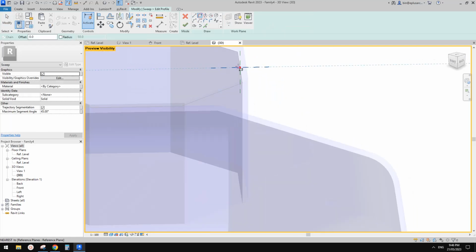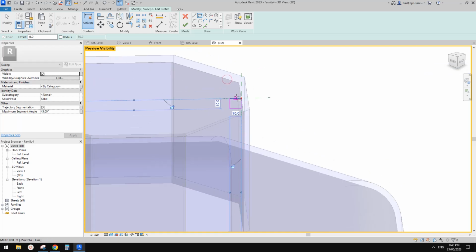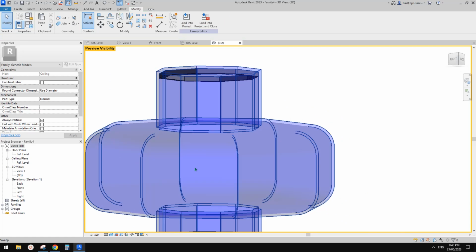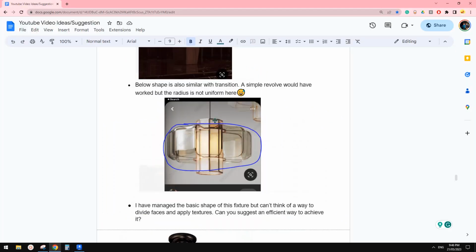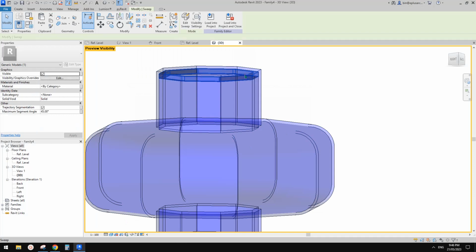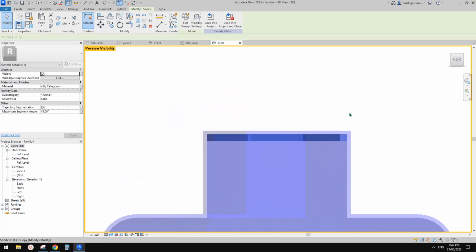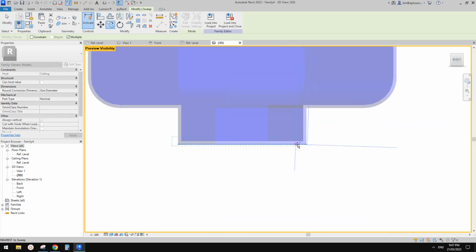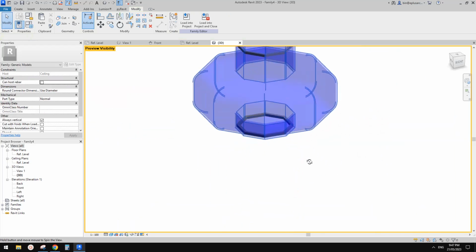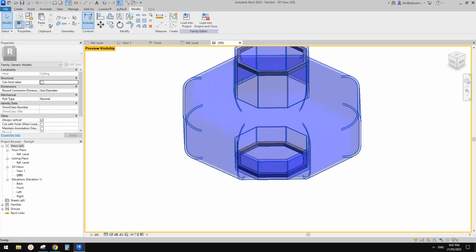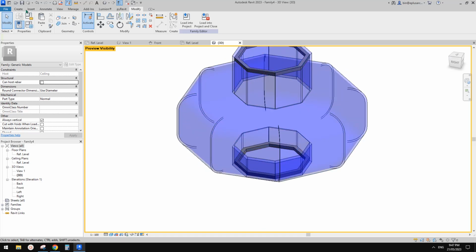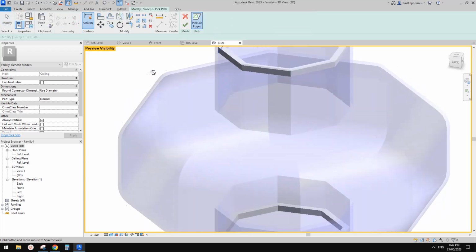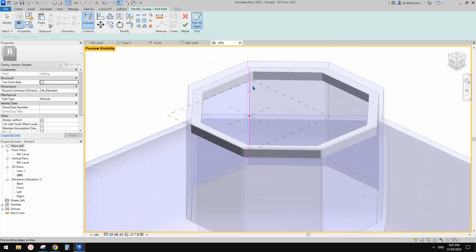I'm going to just add some frame into it, so roughly 10 by 10 finish. So that's some frame inside. Okay, and then let's have a look again. So one there, one there. So you can quite easily either create another one, use pick path, or just simply copy. Okay, and then for the vertical one, we can directly create sweep, pick path as well. Try to pick the internal edge, so this one.